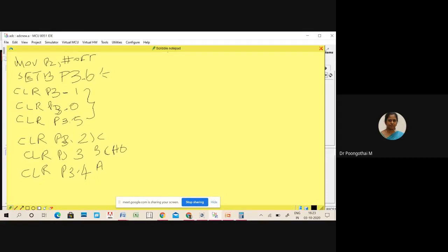So what is the next step after the channel selection? We have to latch this address. So once we have done this, the next step is that ALE has to be high.